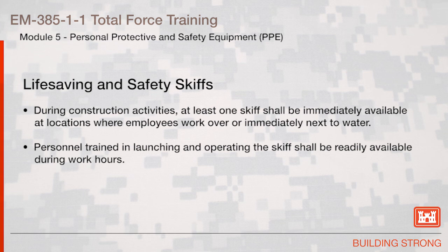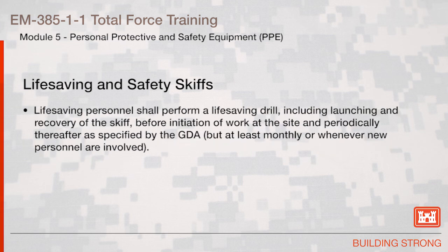Personnel trained in launching and operating the skiff shall be readily available during working hours. Life-saving personnel shall perform a life-saving drill, including launching and recovery of the skiff, before initiation of work at the site, and periodically thereafter, as specified by the GDA, but at least monthly or whenever new personnel are involved.